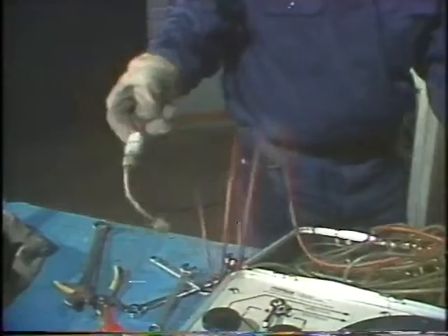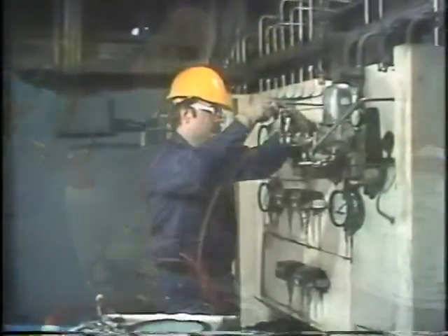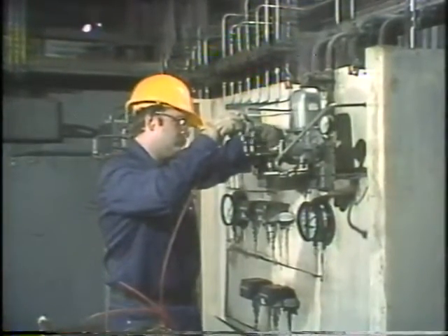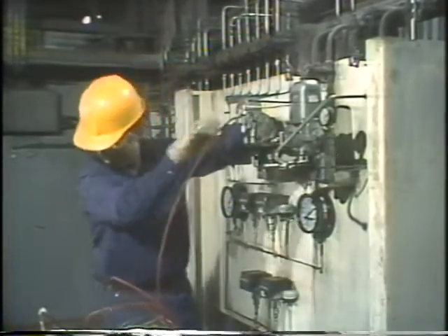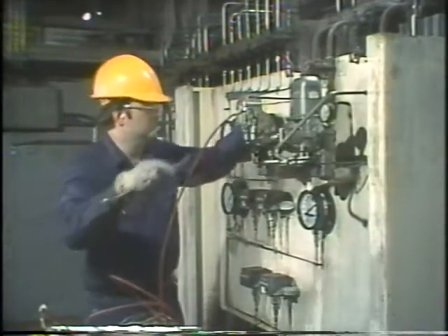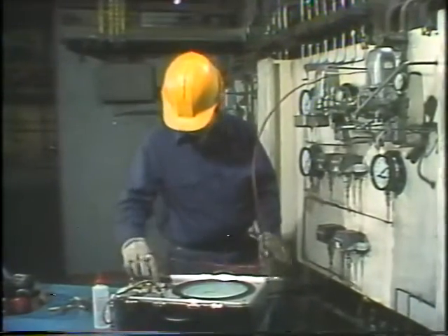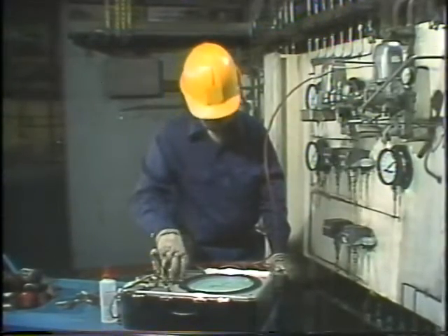Now I'll connect this flexible tubing to the calibrator and to the high side of the differential pressure transmitter. With the low side vented to atmospheric pressure, by applying a pressure to the high side, I will create a differential pressure across the DP cell. I need to be certain that I put the calibrator in the vent position to begin with.